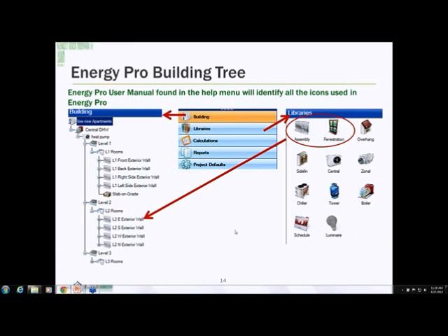So would you perform exhaust fan calculations on a low-rise rehab when sampling is involved? Yes, I would. I like to. I'm a real detailed person, so I like to get as much information about a building as possible. And if I can get information on the exhaust fans, I will include that. And there are ways of showing with the two-model approach how to get savings from the fans. You will get a baseline fan or test-in fan when you model it, and you can do another model, a two-model approach, and compare it and see what the fan energy use is for the improved building.